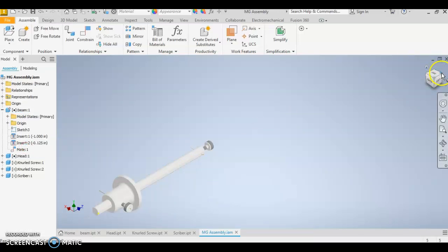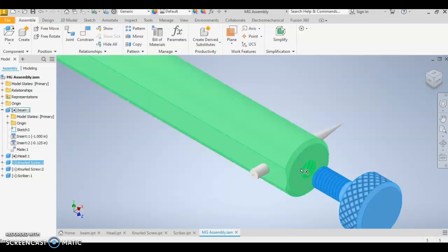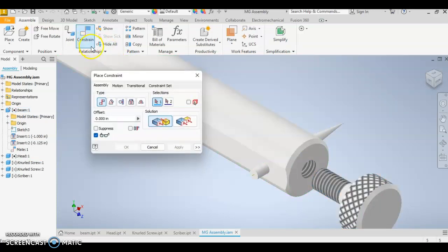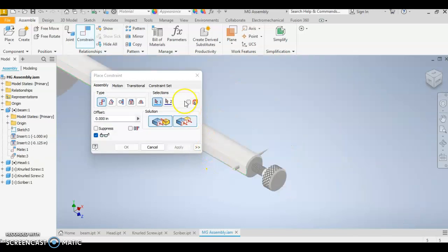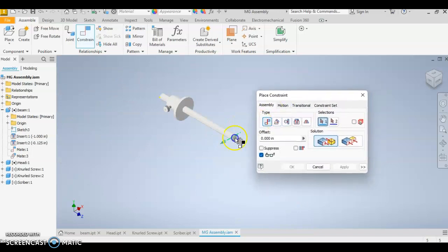So that's in position, but you will notice that I can still move this out. And so I want it aligned properly. And the last constraint we're going to do is a work constraint. We're going to mate, and we are going to mate this work axis right there with the work axis of, and we're going to do opposing the work axis of my screw. They get aligned, and then just simply hit apply. Now your marking gauge is ready. It is assembled, and it's ready to work with further.